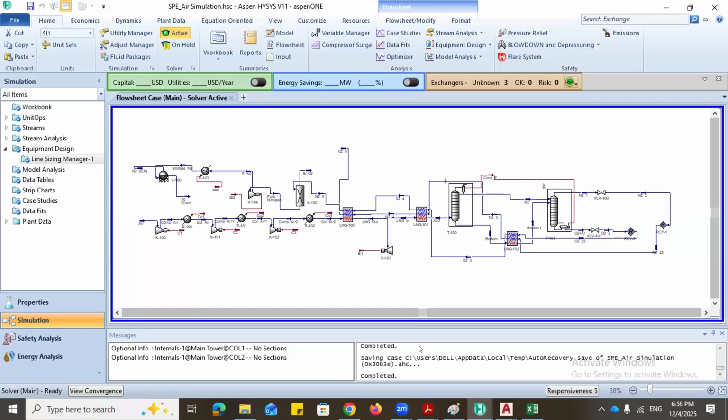Someone said, what of ASME standard? ASME standards are not basically for sizing lines. For example, if you go to ASME B31.1 for process plants and B31.3 for refinery plants, you see details of their velocity criterion and pressure drop criterion.